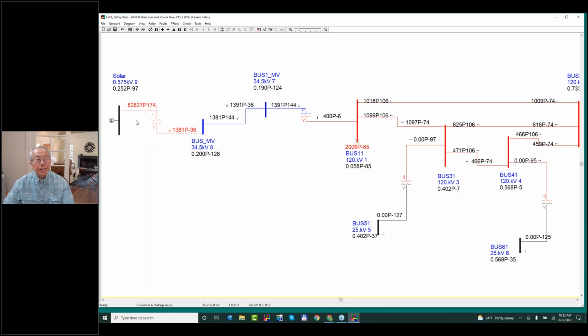And why? Because these machines are usually connected line to line, and without this Y winding here, we know from experience they just plain refuse to work. It's like connecting a synchronous machine to the system and forgetting to ground the neutral. Not only will you get fired, there could also be a fire going on in the generator house. So it is very essential to have this Y-Delta transformer.